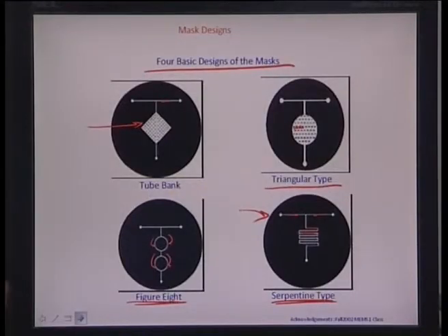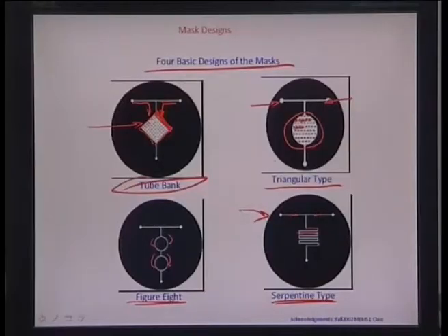The 4 most prominent designs which were proposed are tube bank like structures, where basically there would be small pits in this particular area, and this would be corresponding to small pillars of the PDMS which gets replicated on the top of this. So, this was one illustration where this central area here is introduced with this kind of a feature or a structure, and the flows go from the arms of the T and mix along this particular area which is also along the stem of the T.